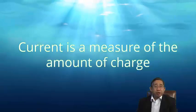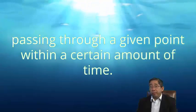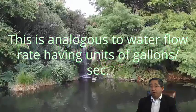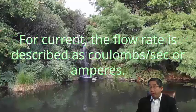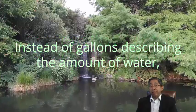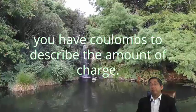Current is a measure of the amount of charge passing through a given point within a certain amount of time. You can think of current as a flow rate. This is analogous to water flow rate having units of gallons per second. Now, for current, the flow rate is described as coulombs per second or amperes. Instead of gallons describing the amount of water, you have coulombs to describe the amount of charge.